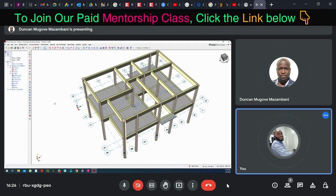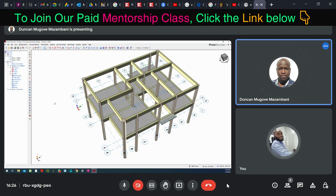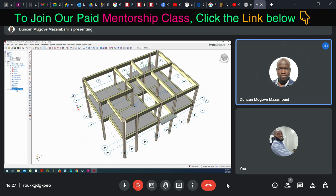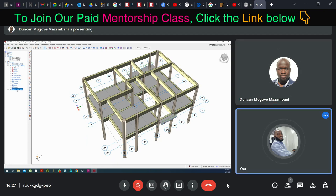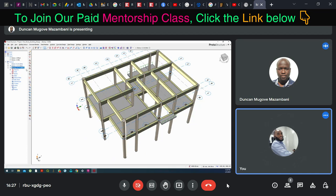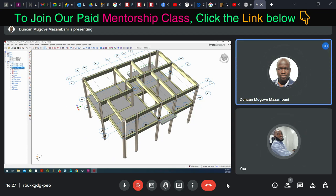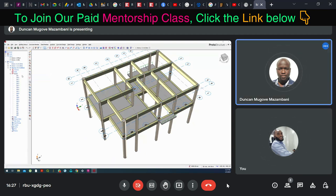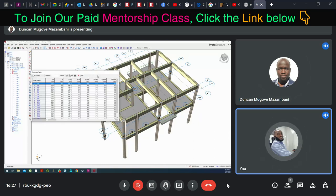Go to your story 2, make your story 2 active. Okay, that's fine. Now go to your beams under that story 2. Right click on beams, and then go to summary table. Yes, summary table, click there. It will show you a dialog box containing all the beams.